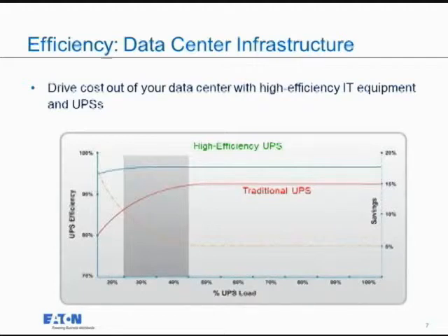And it stays and remains that way up to about 50%, 40%, at which point it will start to decay, right? Typically, it's the magnetic losses in the traditional designs that impact that. So there's no load losses that will occur, and they become a bigger part of the overall, and hence the efficiency drop. High efficiency UPSs, really, we're going transformerless.